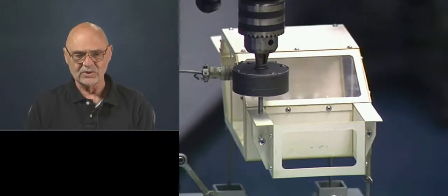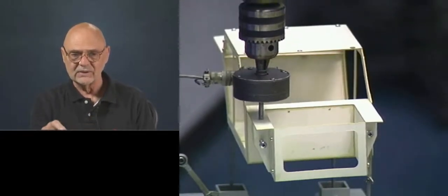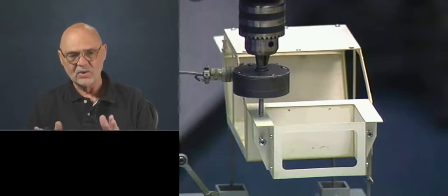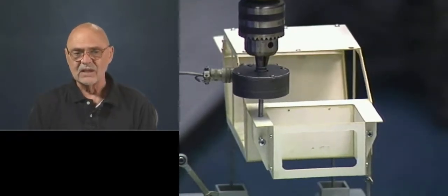You see a little bit of distortion there at the point of load application. Now we've removed the backlight and the windshield. Okay, you see the slope of the curve is much reduced. And here you can see the shearing behavior. Look at the windshield ring, and you can see it's going into that diamond-shaped pattern. So we're getting lots of deformation. We haven't reduced it to 0, but it's not very shear resistant.